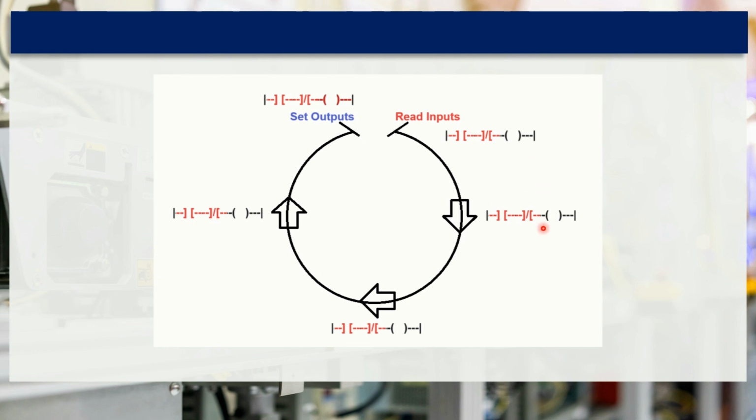Now as it goes through, it doesn't set the output right away, because in this instance it may be high. In this case there might be an identical or a different rung that has the same output, and now it's low, might be high again, etc. But we're going to assume, just for simplicity's sake, we know that the last order wins, but we're going to say that these two are high, and we're going to check it. Yep, still the same, no change, no change. Get to the end, and the last thing it does, it turns on the output.